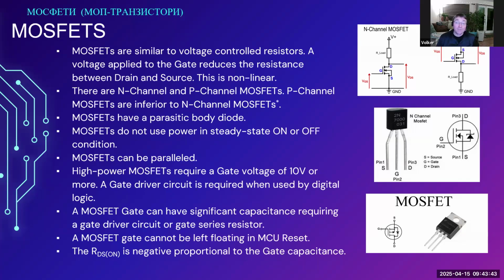And if you use a transistor as a switch and you connect it to a microcontroller, just the base resistor is good enough. In reset, the pin is floating, basically disconnected, and the transistor does not get its base current, so it does not turn on.